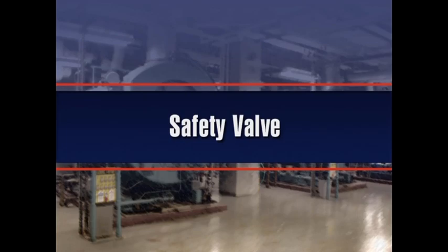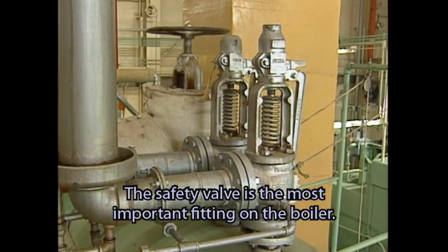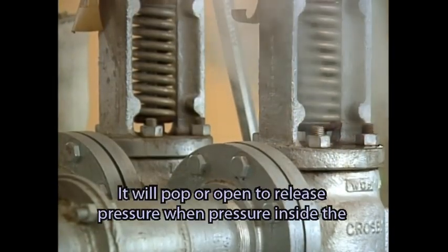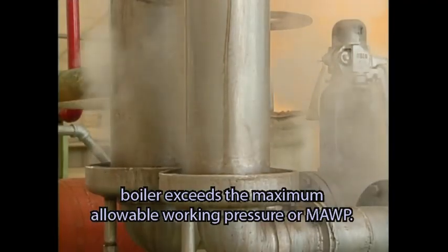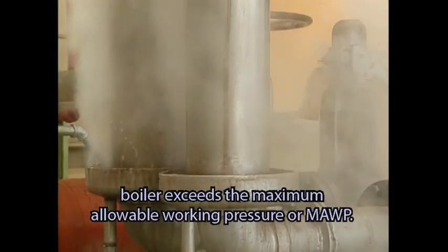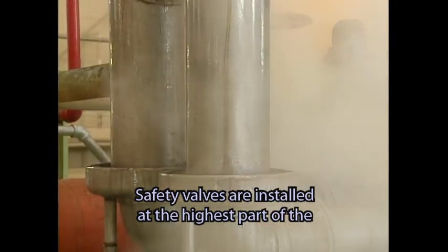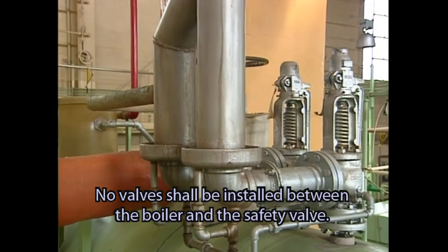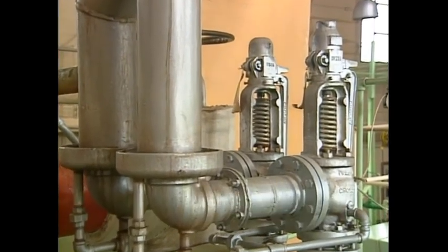Safety valve. The safety valve is the most important fitting on the boiler. It will pop or open to release pressure when pressure inside the boiler exceeds the maximum allowable working pressure, or MAWP. Safety valves are installed at the highest part of the steam side of the boiler. No valves shall be installed between the boiler and the safety valve.